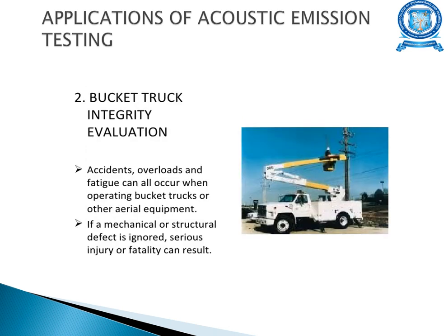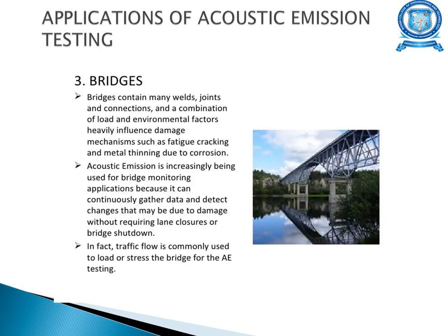Next is the bucket truck integrity evaluation. Accidents, overloads and fatigue can all occur when operating bucket trucks or other aerial equipment. That can be detected by this acoustic emission. And if a mechanical or structural defect is ignored, serious injury or fatality can result. So all these can be tested using acoustic emission.